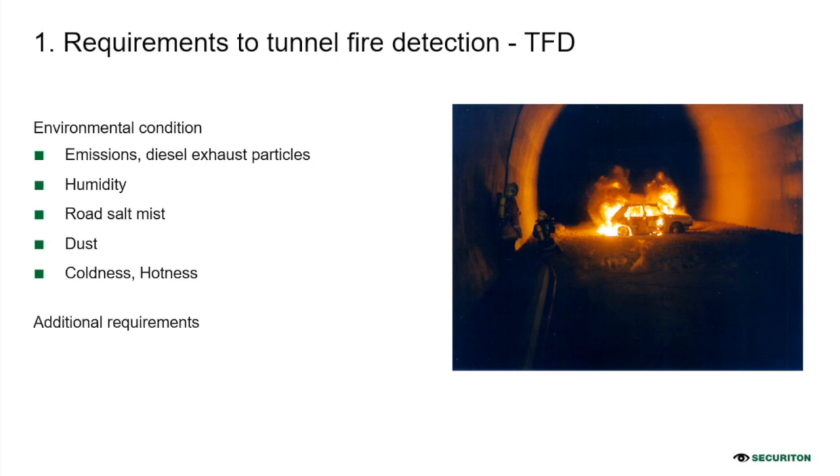Then there are also additional requirements. For example, the integration of such a system into the operating system. That means the system must have some interfaces. Today, it's very usual to have Modbus TCP/IP, or it could also be RTU. There's also BACnet, but most of the integration today is done by Modbus. So this is also important, that it can be easily integrated into the SCADA system.